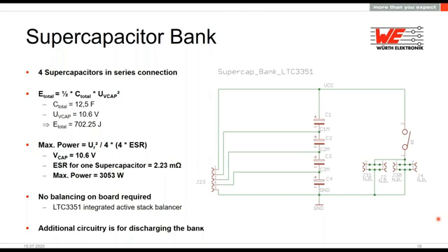On the bank, there is no onboard balancing because the IC from Analog has an integrated stacked balancer. And what you see here with this circuitry with the plug is just so that I can discharge the bank manually when there's some issue or when I want to send it somewhere.